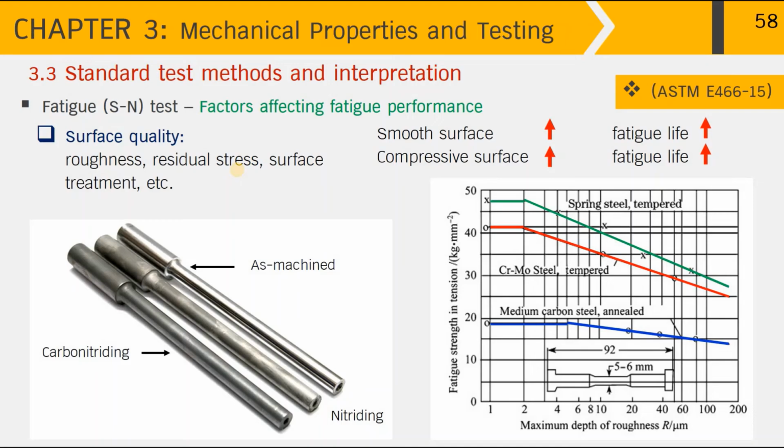It is the negative values. Therefore, in order for the specimen to fail under fatigue, it has to withstand a greater fatigue stress on its surface. Therefore, the greater the compressive surface stress, the greater the fatigue life the specimen will obtain.